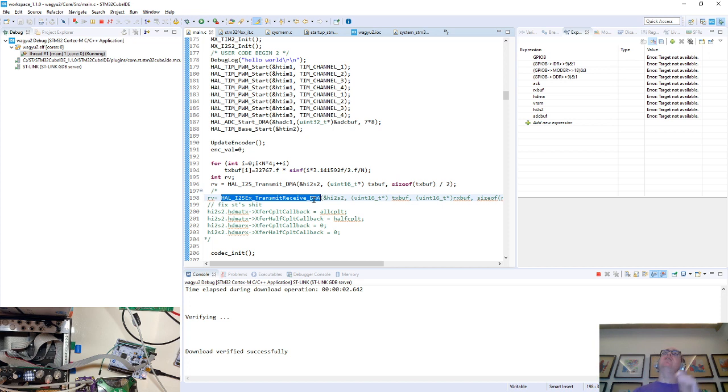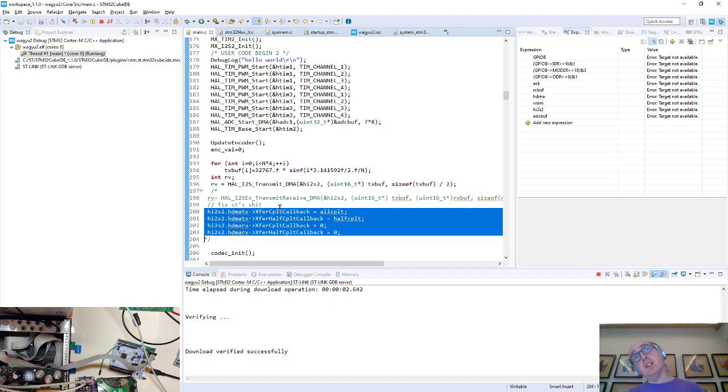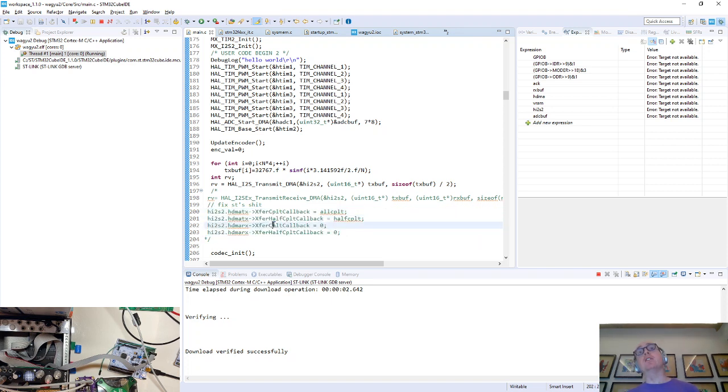So you basically get two callbacks for each. You get complete, complete, half, half, complete, complete, half, half, which is just bad. So the most elegant fix is that you replace their 4 callbacks directly with your own, and that removes one layer of indirection, and it removes their bug, and it removes the double call, and you can then do full duplex, by which I mean you can record and transmit at the same time.